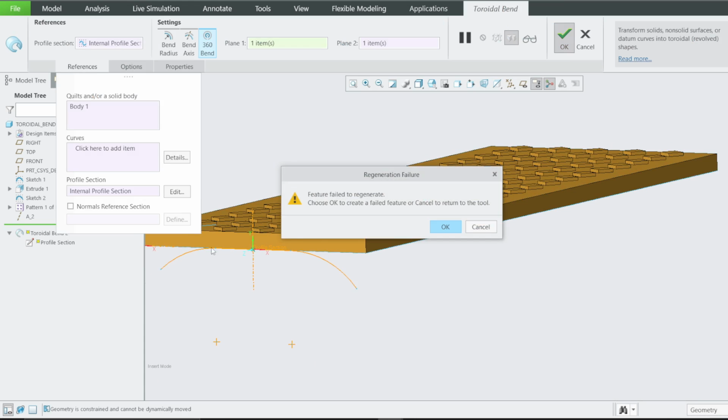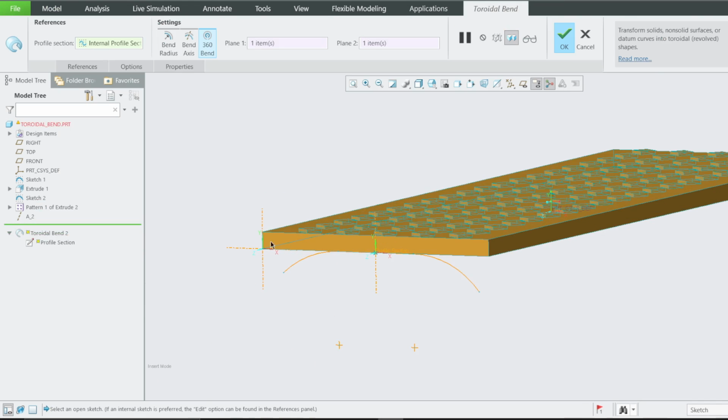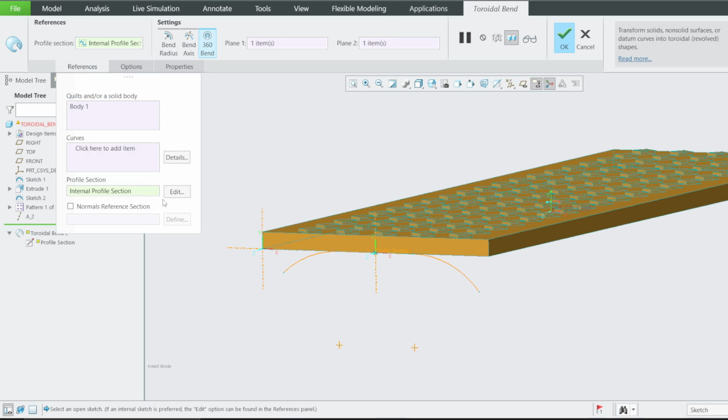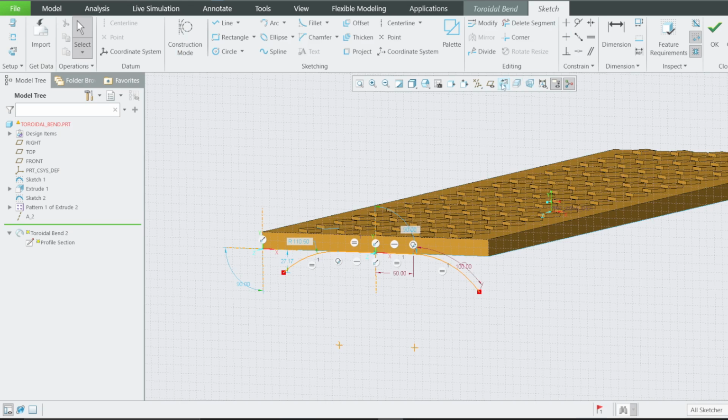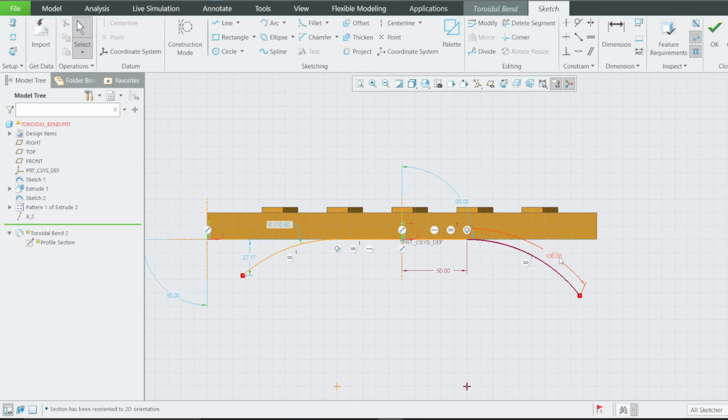Because the sketch you define has to be exactly the same length as this profile here. Therefore, if you go back to the preferences here, you see now this one is 110, this one is 100, this is 50, this is 50, this is not 100.